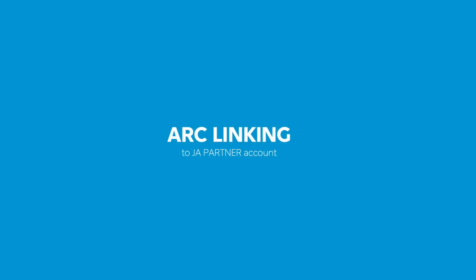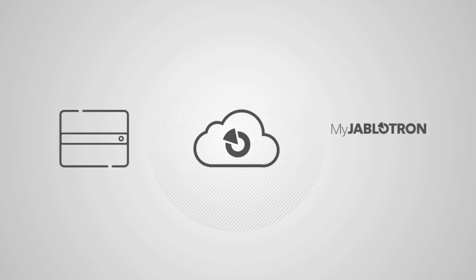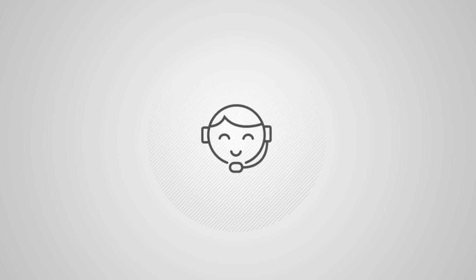There are three main ways the control panel communicates with the alarm receiving center, also known as an ARC. Some systems don't communicate any data to the ARC, some are connected via the Jablotron Cloud, and some are connected directly. Let's have a detailed look at these options. The basic and most simple way is to connect the control panel with Jablotron communication to our cloud. All data that are needed by the My Jablotron and My Company applications are transferred via channel 1 and 2 as mentioned at the beginning. However, no data are transferred to any ARC. This can be changed anytime later on when the customer decides to use a cloud ARC.